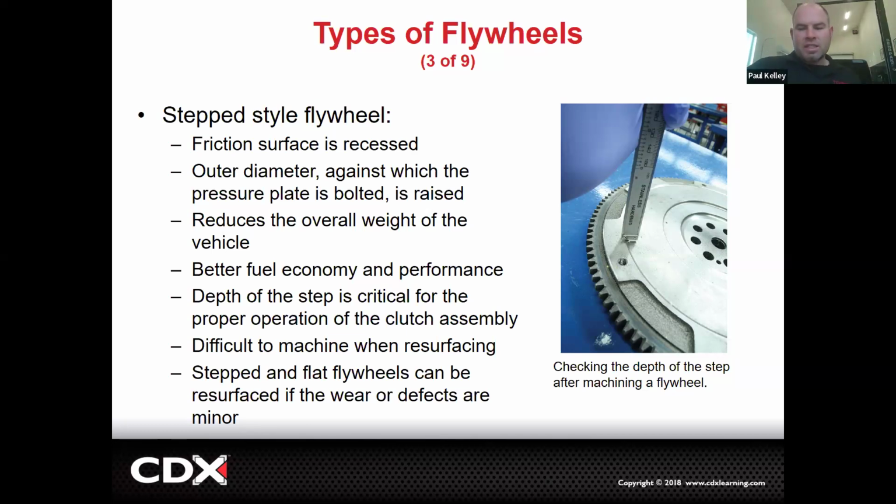Make sense? That's exactly what I got with this Jeep, except I know it's not a machined flywheel because I didn't machine the flywheel, right? So the symptom of an improperly machined flywheel, if they over machine the step, if they over machine the mounting surface, but they under machine the friction surface, it'll give you the exact same symptom as air in the release line, in the clutch cylinder line. It's kind of crazy, but that's why you have to understand both.